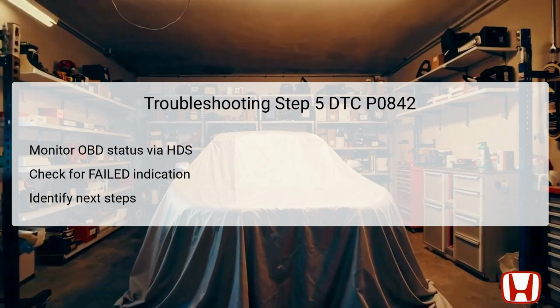In this scenario, looking for an intermittent issue, such as a short circuit to body ground in the wire between the switch and the powertrain control module PCM, is advisable. Conversely, if reported as not completed, it would require a return to Step 4 to ensure accuracy in readings and tests. Accurate diagnosis at this stage is critical for determining if further repairs are necessary.